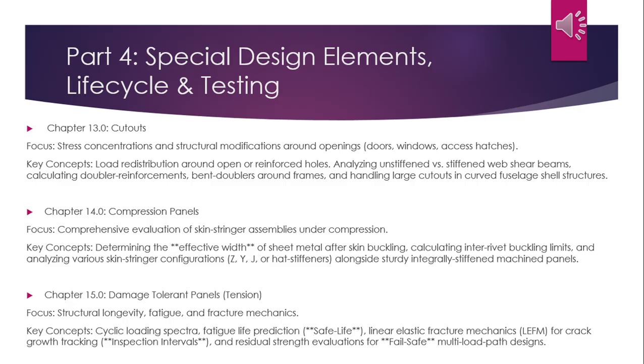The key concepts is like load redistribution around open or reinforced holes, analyzing unstiffened versus stiffened web shear beams, calculating double reinforcements, bent doublers around frames, and handling large cutouts in curved fuselage shell structures.